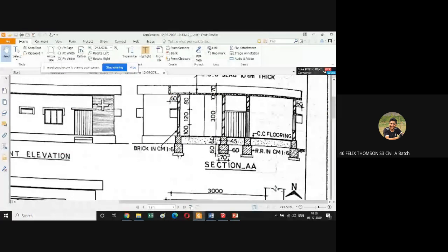Wall bearing. Yeah, it is wall bearing. There are no columns. It is fully load bearing, wall bearing structure. Therefore, you don't need the footing, RCC footing. Instead, the loads transferred to the walls are then transferred to the rubble masonry that is constructed underneath it. So the bottommost part is the 10 centimeter thick PCC layer. Plain cement concrete PCC layer 1:3:6. 1 cement, 3 sand, and 6 coarse aggregate.